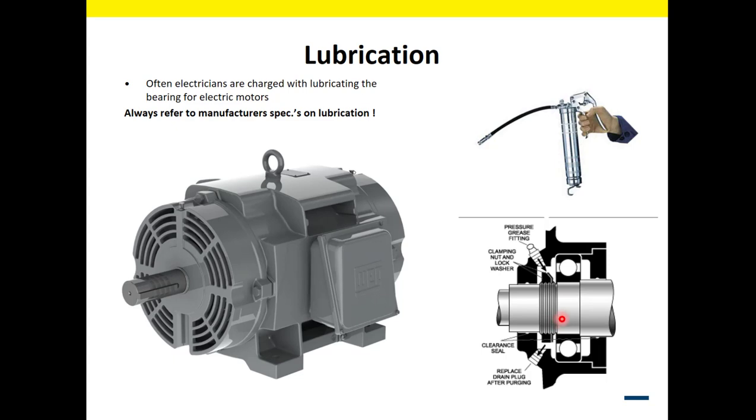Also, when lubricating these, it's easier and you get a better lubrication job if you do this while the motor is running, or at least turning the shaft at a decent slow RPM, but a safe RPM.